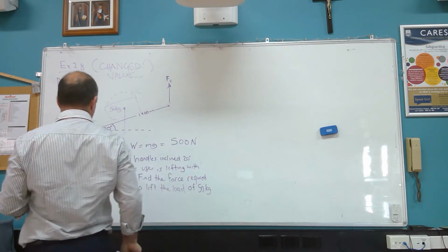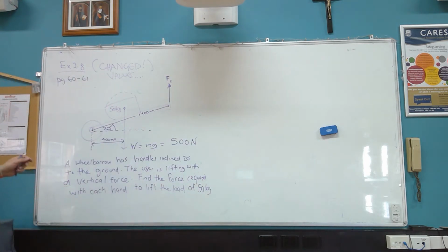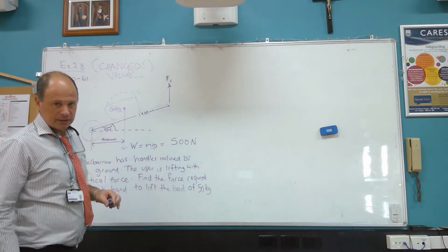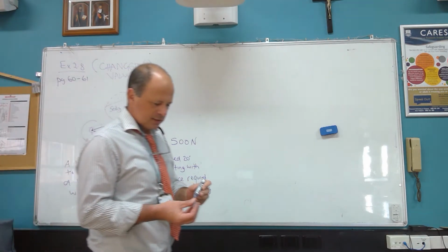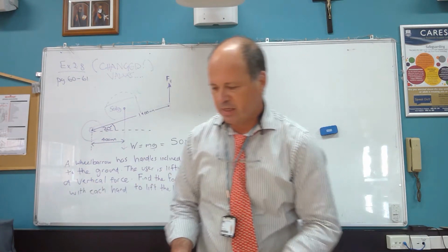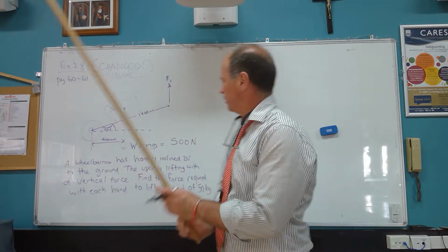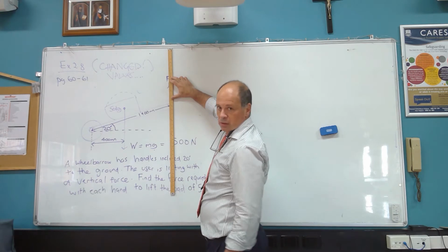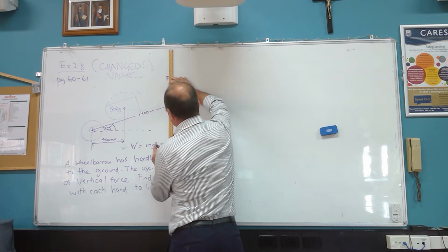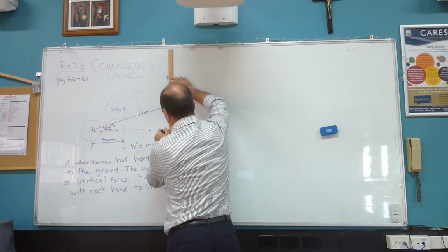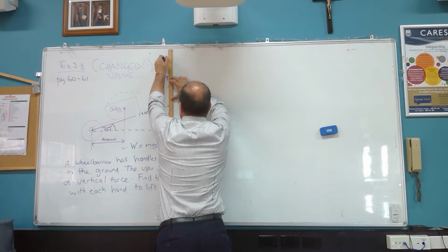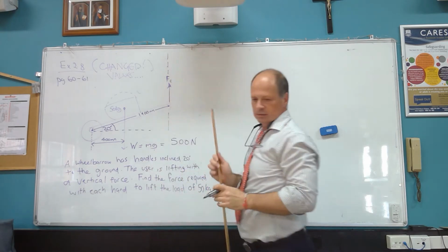But the problem with this problem is that when we're looking at our distance here, our distance is not perpendicular to its distance. So how do we find the perpendicular distance? Well, you remember that it has to be 90 degrees to the pivot. So remember the first thing I said to do is take your line of transmissibility, this is straight up and down, and you might want to just make sure that you extend those lines, okay?